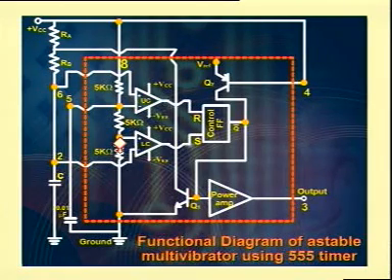Now if modulating signal is applied, if an amplitude of the modulating signal equal to 2 volts, then it will be directly connected to the upper comparator reference voltage terminal. Therefore the upper comparator reference voltage becomes 12 volts and lower comparator reference voltage also changes, now it becomes 6